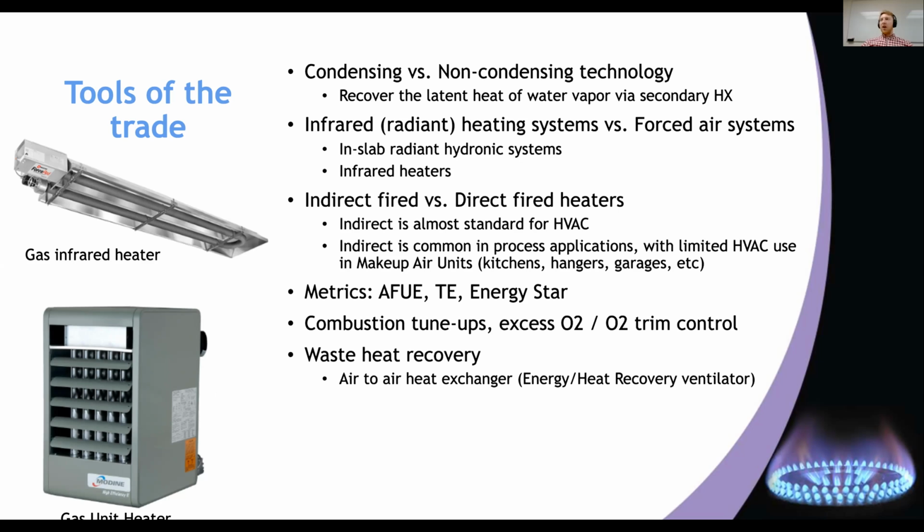And usually when we're talking about heating, humidity isn't as much of a problem, because adding heat to an air system will actually reduce the relative humidity. You're not adding water to the air, but you are expanding the capacity of the air to retain water by raising it to a higher temperature. So usually we deal with humidity more when we're going through a cooling sequence, because we have to remove humidity in the air. As we cool, the air becomes less able to hold water, and therefore we have to remove water from the air while we're doing comfort cooling.